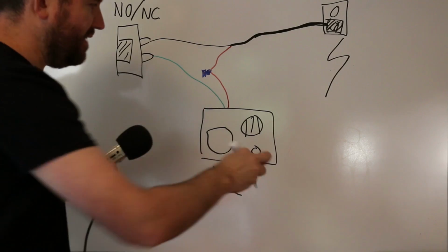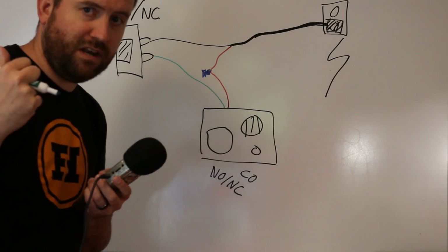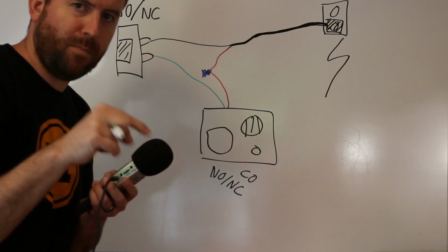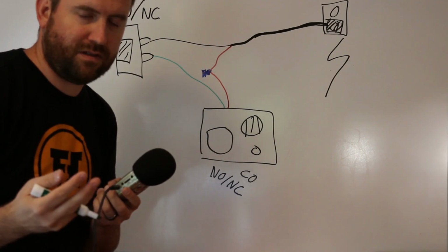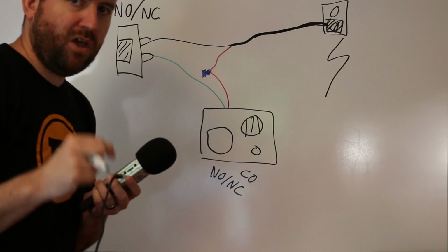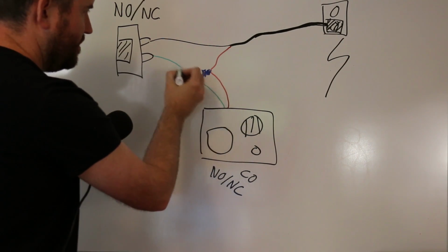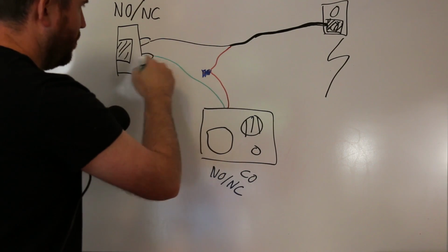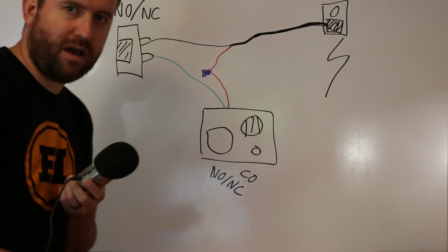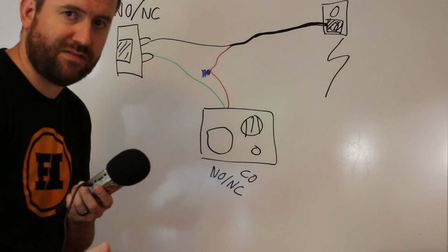Okay, so when you hit the button, beep, it rings a phone. You pick it up, hello, oh, you need to be let in. All right, hang on one second. Boop, boop, you enter a DTMF code. I usually like to use 99 to open a door. When you do 99, it applies power to this green line here, which applies power to the door lock, which opens it up. And typically it's on a timer of 5 seconds or 7 seconds.